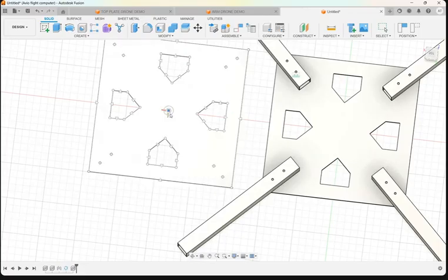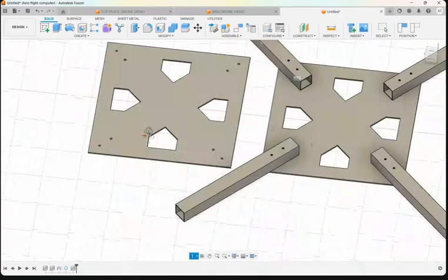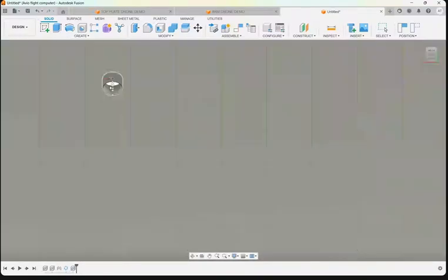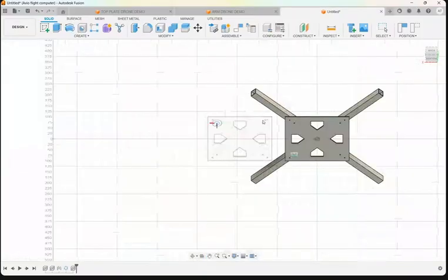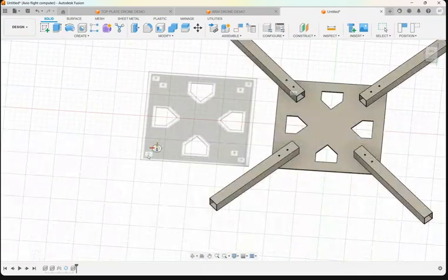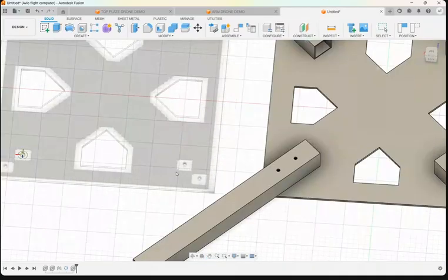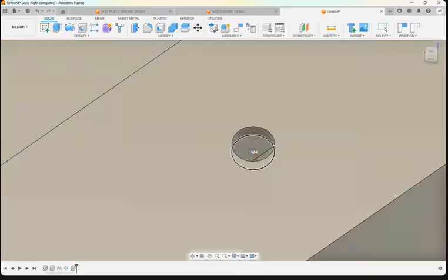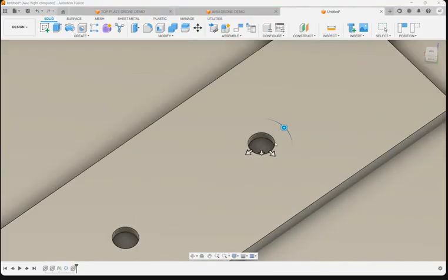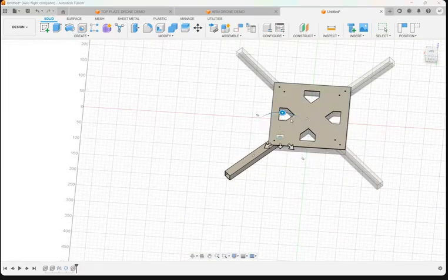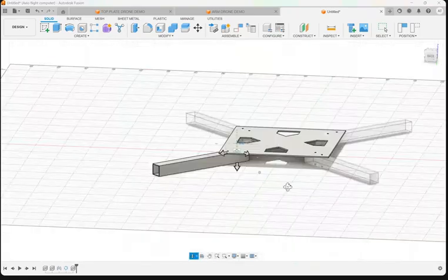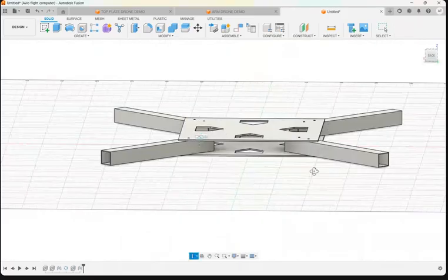Sorry. Now this plate of ours, suppose this hole of this plate, this particular circle will be matching to this particular part, because if I match the top circle here, the plate will be attached inverted, and the orientation will not come properly. So we'll select the circle and select this circle, so it has automatically come on top, and now we can revolve it around and make it point perfectly, align it, and okay.